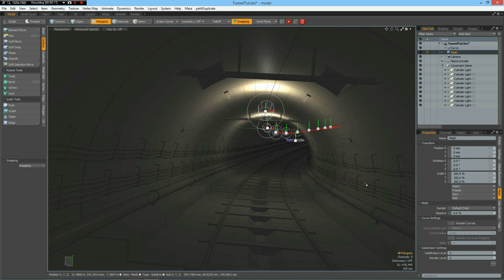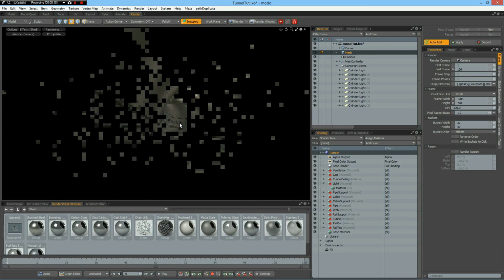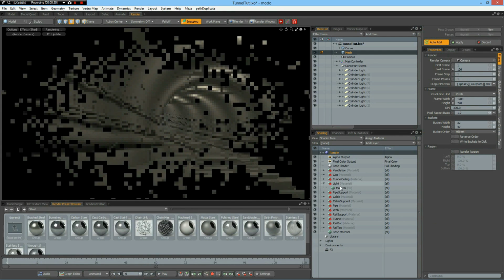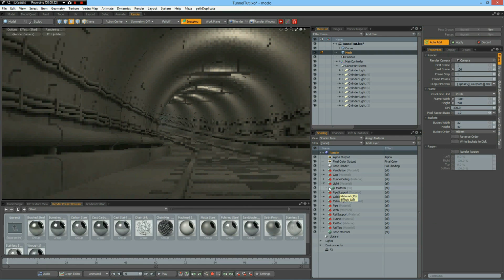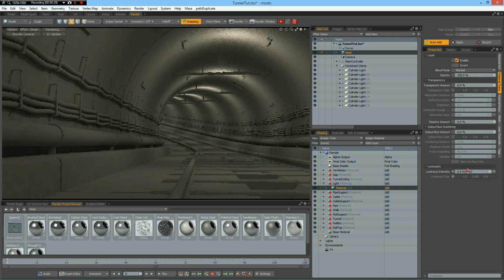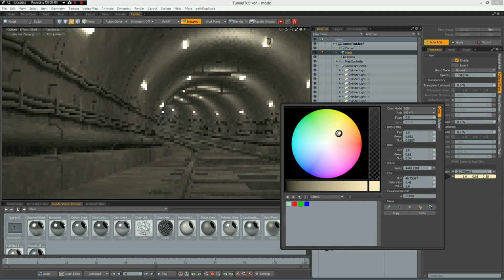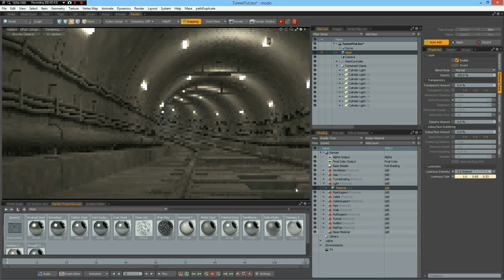Maybe we can even take one more out here, delete, and I will now assign some lights. I explain the light material. Go to the material, select this and give it maybe 3 watts per square meter, and take a warmer color also here.